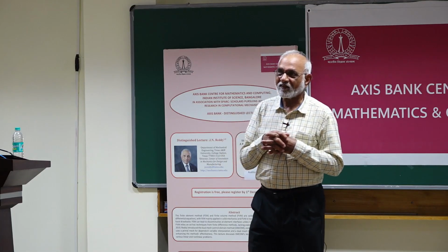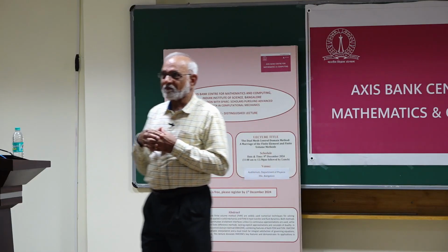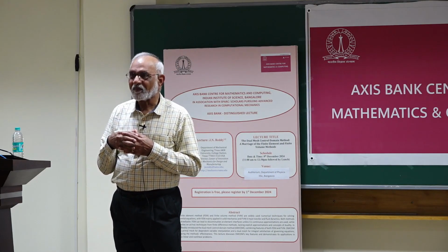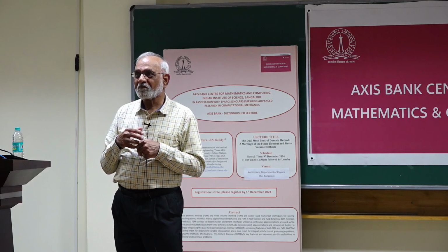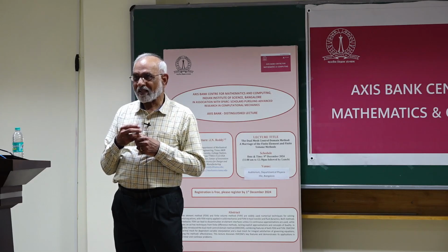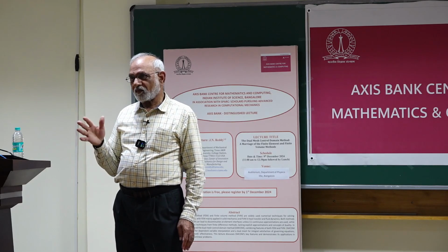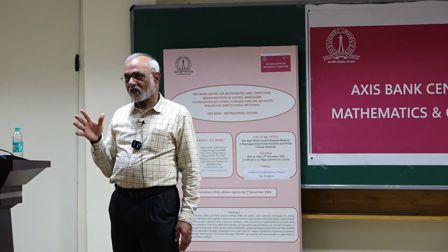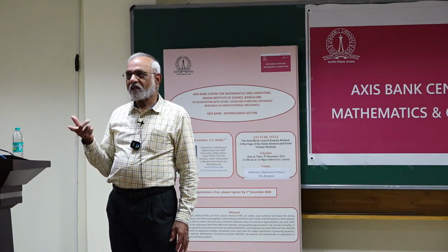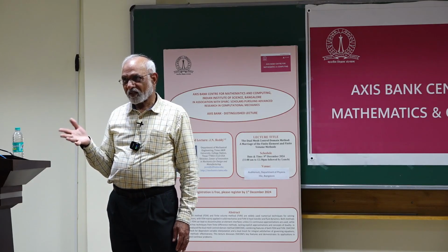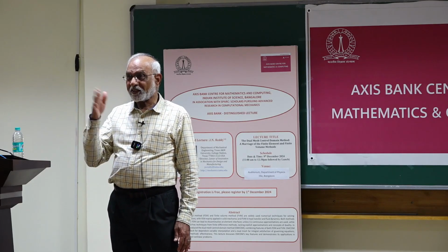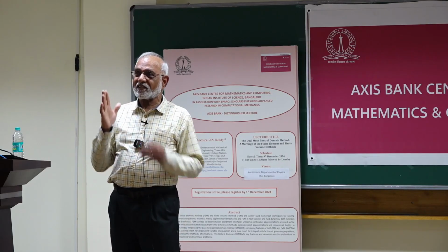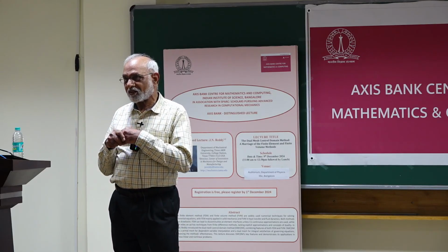Okay. All right. And sir, one more question. Suppose we have a shock wave within a control domain. If you want to handle the shock wave, how are you calculating derivatives? Okay, this is physically very interesting. When we say shock, there is no discontinuity in the real world. It's only sharp. So the degree of sharpness, we say it is discontinuous. There is nothing discontinuous about it.